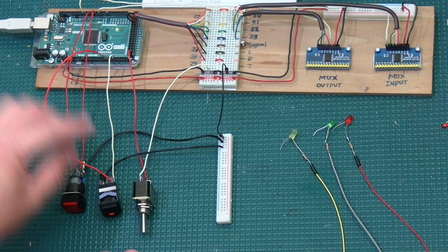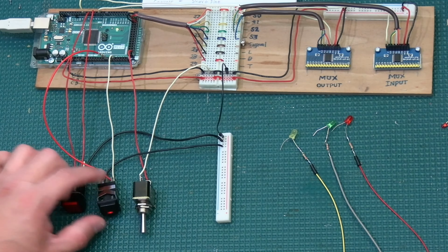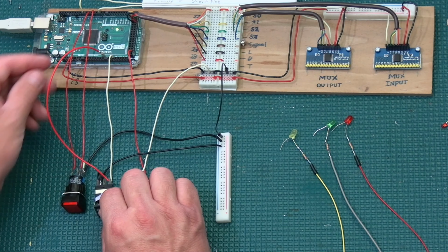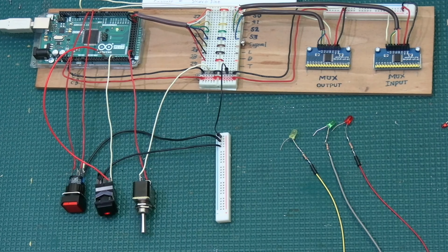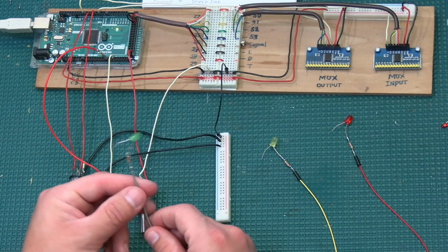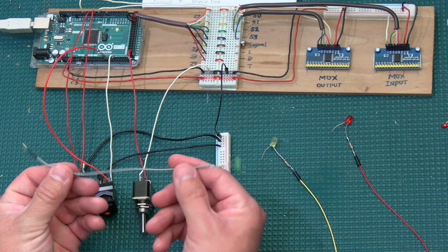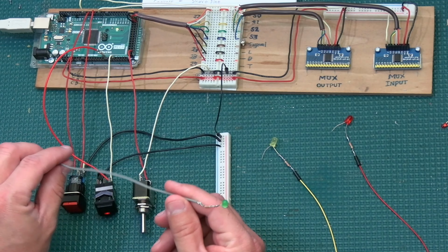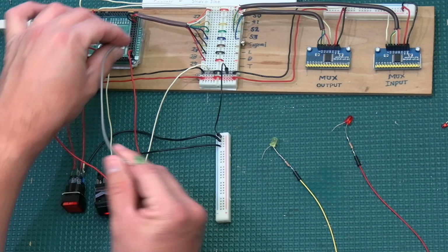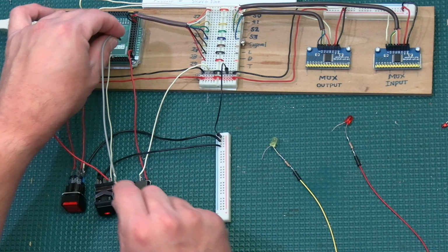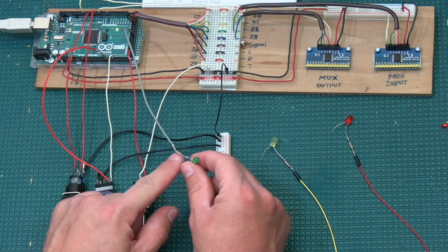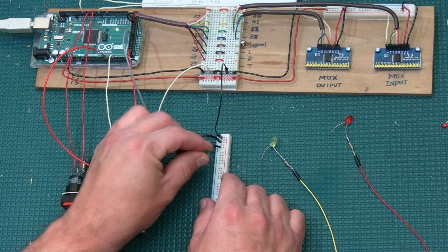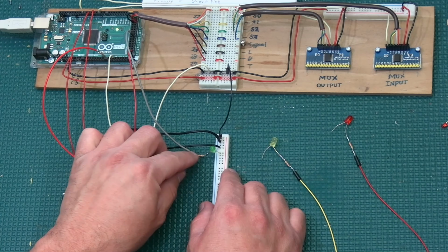Okay. For some reason it's lighting up a little bit, which is kind of weird. It's not supposed to be doing that, but okay. Let's see what happens. All right, now we're going to go ahead and do the green LED right here. The green LED is for the flight director, to show when the flight director is on. So that's going to be on number 41. Let me go ahead and put that there. 41, that's the positive side with the resistor on it. And then this is a common ground, so I'm just going to stick it in there.